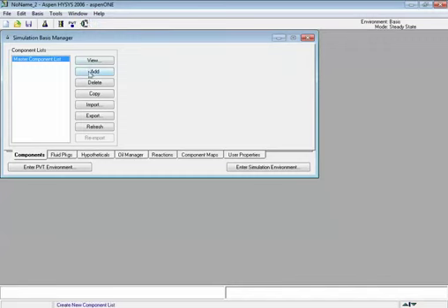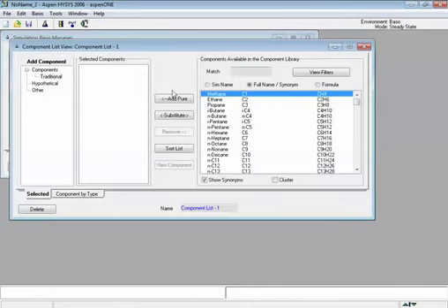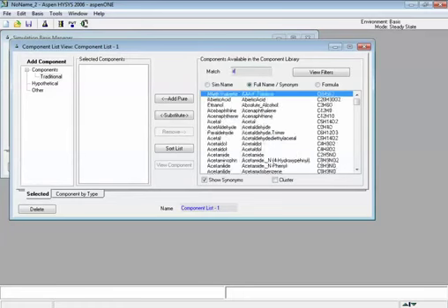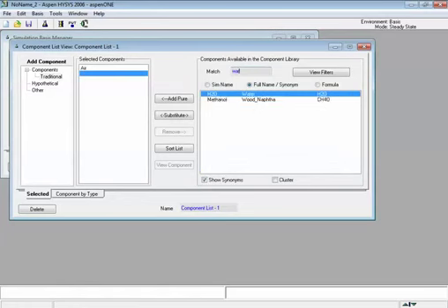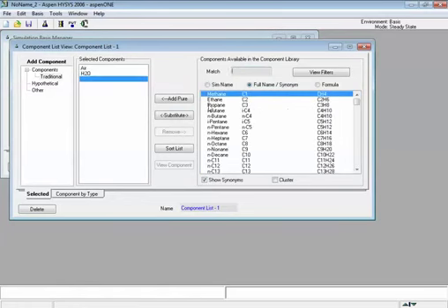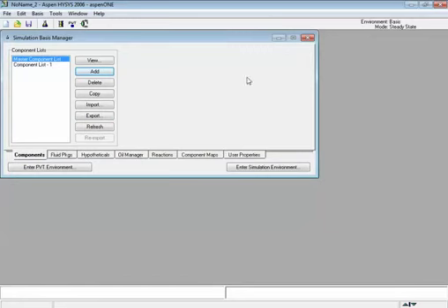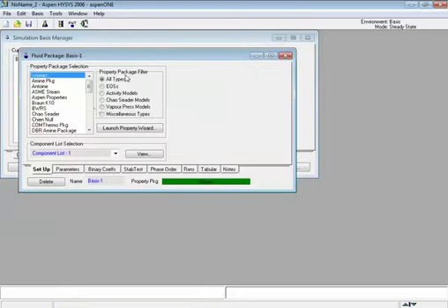We first prepare a steady state simulation. Here I would like to add some components, air, some water. Air is dispersed into the water. When adding the component list, that is the basic step of steady state simulation or any simulation. You have to first include all your system components. What are the systems you have, how many components you have. Then you have to add a property package to the system components by which their thermodynamic property will be calculated.